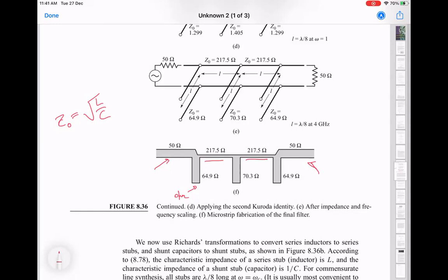But for the standard circuit boards, which one uses for standard thickness and standard dielectric constant, it becomes difficult to go below 20 or above say 120. And on the other side, on the high impedance, if it becomes like a very narrow piece of wire, then it just sort of stops seeing the ground, and then you can have radiation into free space. So that's the other side of why you cannot go to very high impedance.